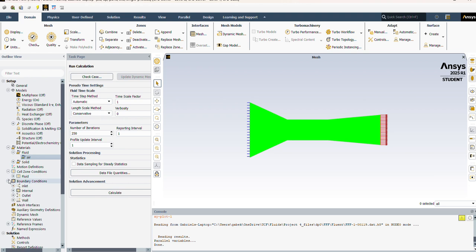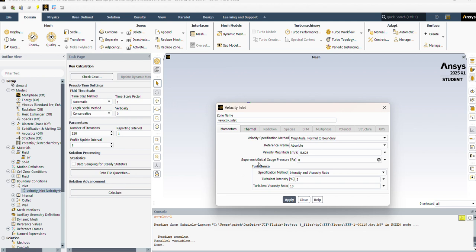Yeah, and boundary conditions for the inlet. They want the test section velocity to be 15 meters per second. You have to use the height ratio between the contraction cone and the test section to get your inlet velocity so that it becomes 15 meters per second in the test section, and that means the inlet had to be 5.625, because using mass flow rate and everything like that, it's a ratio.